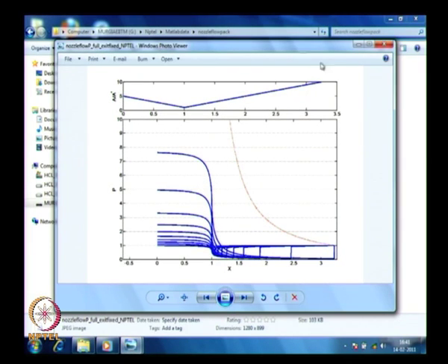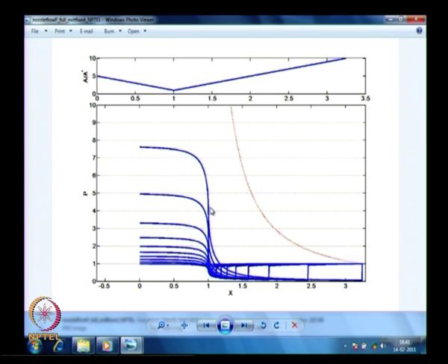We look at this particular picture where I am having the same nozzle. I have just plotted it differently now. We are keeping the exit pressure exactly the same as the back pressure, and the flow wants to meet this pressure whatever happens. What we are saying is, it starts with a slightly higher value, it goes down and goes back up, it is all merged inside here, you cannot see very clearly. But say about 2 or so, it is going to become supersonic, have a shock and then go through the subsonic path. And as I increase my P naught, now my shock is pushed more downstream.